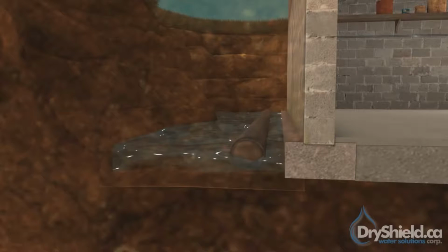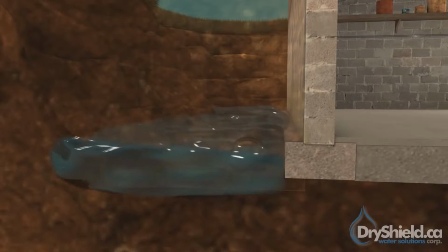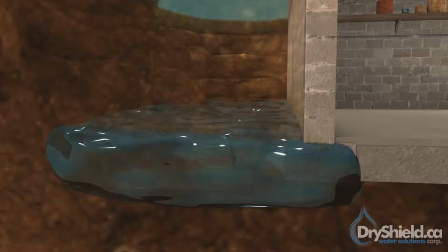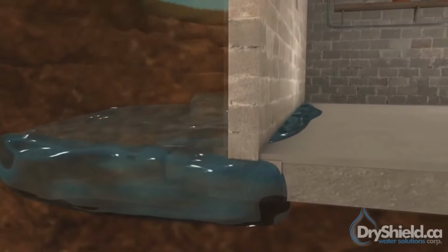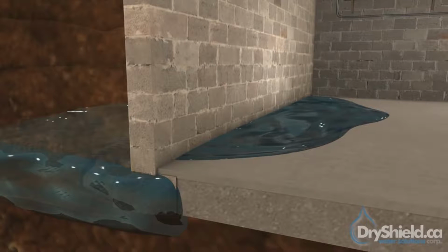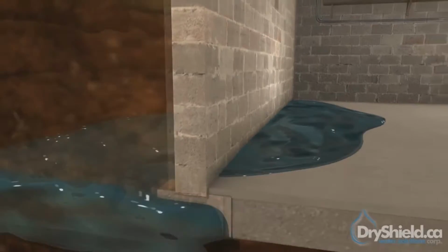Once the weepers clog, the water will begin to build on the outside of the foundation, causing hydrostatic pressure. Once the pressure builds, water will enter at the floor wall joint, either from underneath or over top of the footing. Over the past few decades, our research has allowed us to incorporate the highest level of waterproofing technologies and procedures to date. Let us show you how the external procedure is installed.